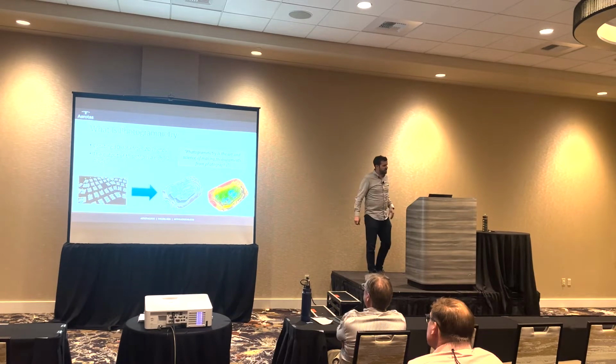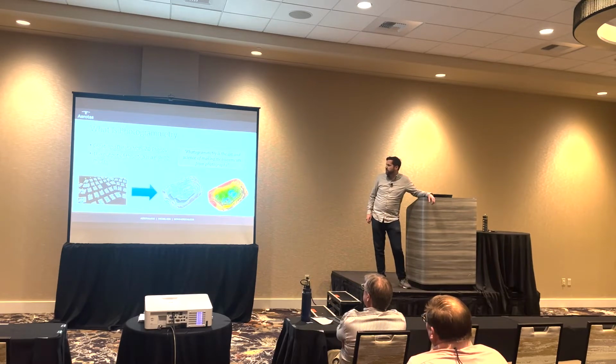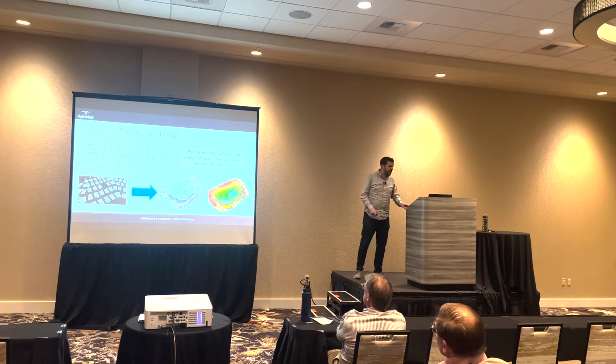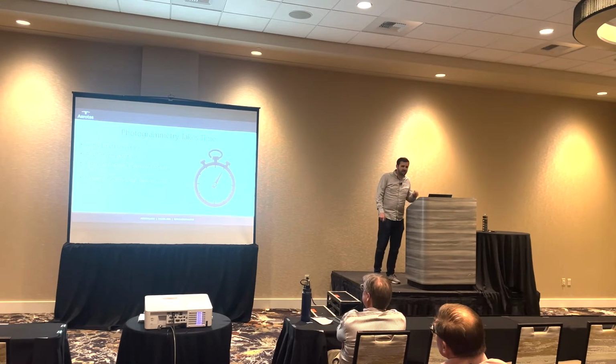So photogrammetry is the art and science of making measurements from photographs. So that's where it goes from the photos into an orthophoto, point cloud, and a digital surface model. The output is that rich 3D surface model. One of the things to be aware of with photogrammetry is it takes kind of a lot of time. It takes just a little bit of human time. A really skilled photogrammetrist will be able to mark control points, get your datum set up, and throw it into a processing server really quickly. But it takes an awful lot of computer time.